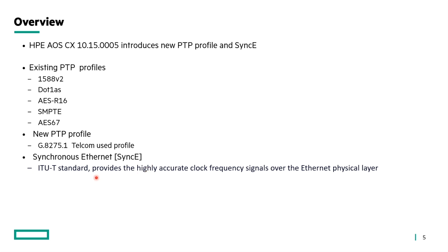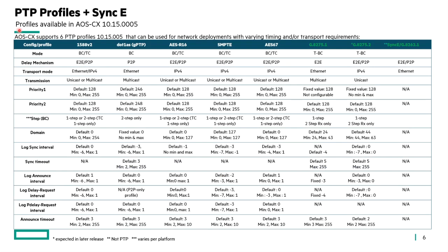SyncE is an ITU standard which is based on frequency and gives us a highly accurate clock. So just to summarize, we're going to be talking about PTP and SyncE. As of 005, I've listed here all the types of profiles that are available in our CX products, but today we're concentrating on this first green column, G.8275.1, and SyncE, which is the last column and isn't a PTP profile as such.